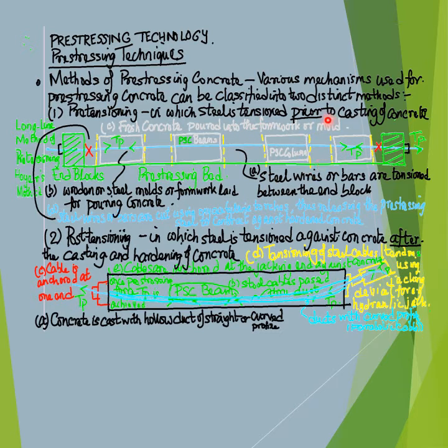Consequently, pre-compressive stress, termed as pre-stress, is induced in the pre-stressed concrete elements such as the pre-stressed concrete beam elements and the pre-stressed concrete column elements shown in the schematic diagram for the pre-tensioning or pre-stressing bed, typically implemented in the long line method of pre-tensioning or the Hoyer's method of pre-tensioning concrete.